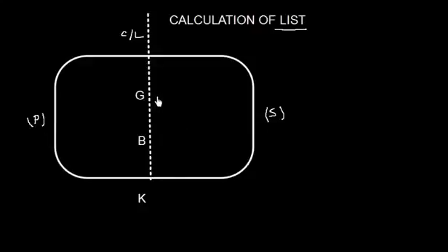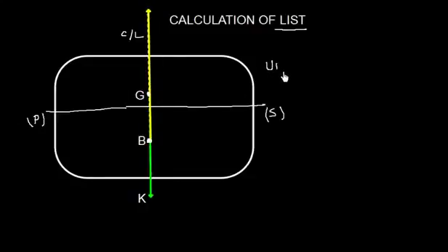port side. So weight will act vertically downward through the center of gravity like this. And if the vessel is floating at some draft, say for example, let me just mark here, the geometrical center of this underwater volume is going to be the center of buoyancy, say somewhere here, and a force of buoyancy will act vertically upward through that. The vessel is called upright.